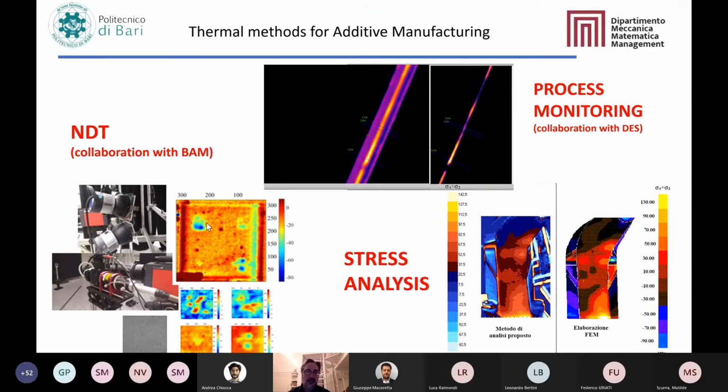So we got an example of some defects inserted on purpose, or at least we try to insert on purpose. The defect inside is quite a straight sample, and so we obtained very good characteristics that had a very consistent comparison with the radiographic method, CT, and we obtained the possibility to measure and characterize also some pores and keyholes.